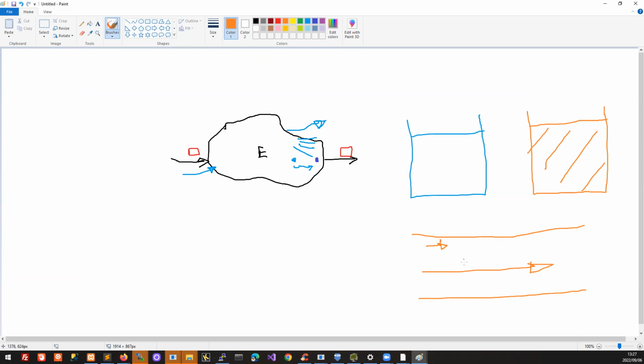But because of high viscosity, the fluid in the center line will tend to drag the fluid among its neighbors forward as well. So you will have a viscous drag of the fluid, and so that will be a momentum loss for the high velocity parts.